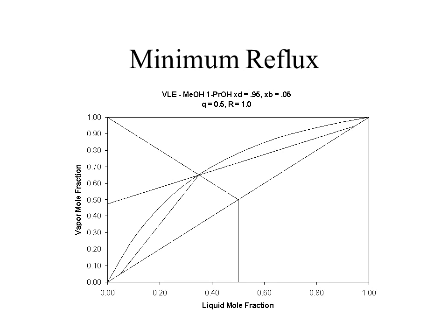And so this is the minimum value for the reflux ratio, which actually would require an infinite number of stages in order to achieve this. And so you cannot go to a value of reflux ratio less than that minimum value. And that would be determined based on the intersection of the Q line and the equilibrium curve.